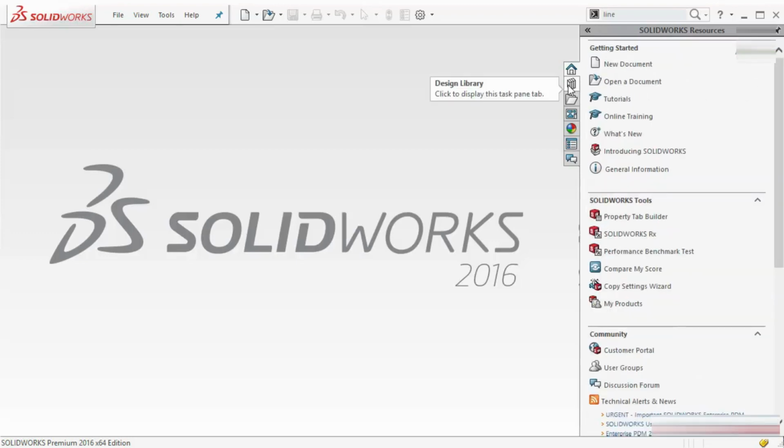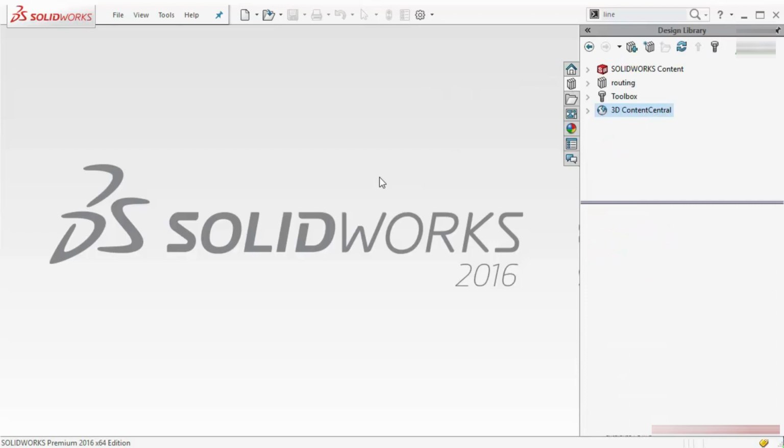The next tab is, which is really very important, design library. Library means which part or anything you want to reuse. You can reuse any routing part from here, or if you want to reuse your any hardware related thing, as for example nut, bolt, washer, something like that. In that case, you have to use this toolbox. You can set up your own toolbox if you want. This is highly customizable. Also, if you want to access 3D Content Central, you can also do that from here. If you want to create a new library, you can also do that by using this option.